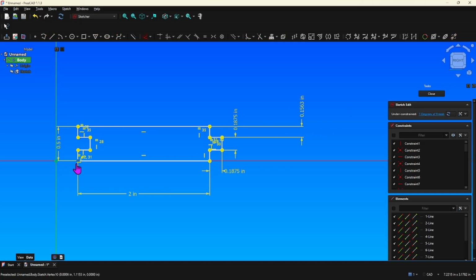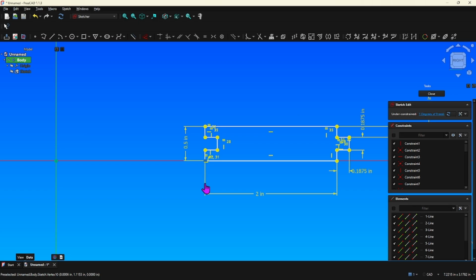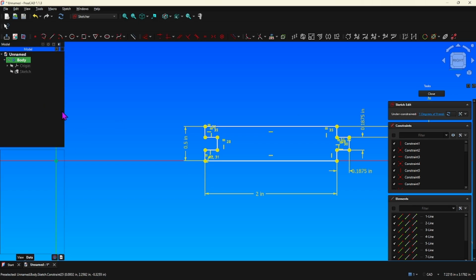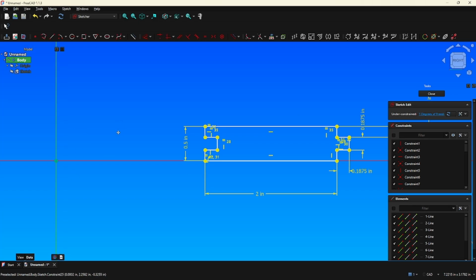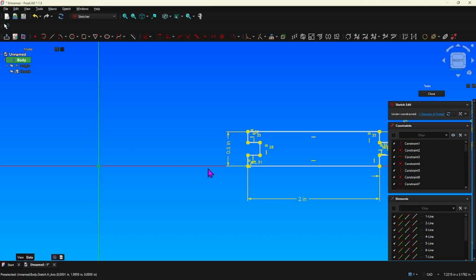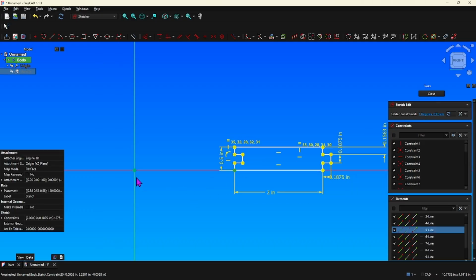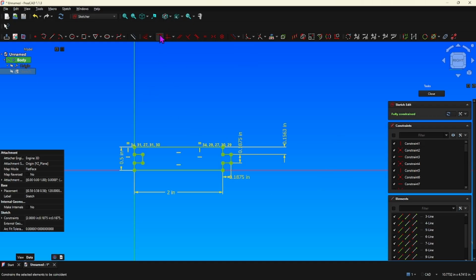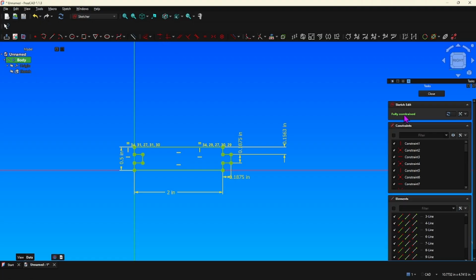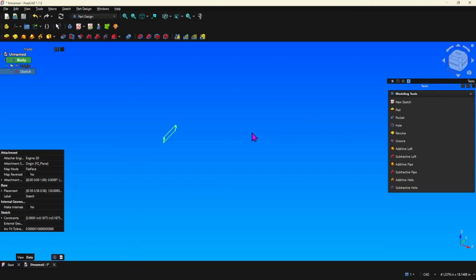And I can just go ahead and make it coincident to that origin point, or I can give it a dimension. Let me move this over some from here to there. It doesn't matter, but for simplicity, I'll just select that point, that origin intersection, and we'll select a constraint of coincident, and that puts it there. It's fully constrained. I'll close it.